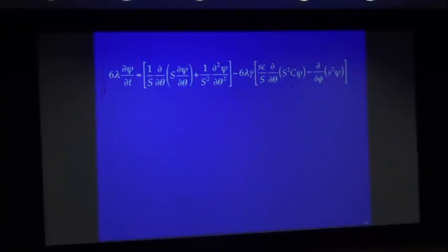This term here, you notice, does not contain the shear rate. This is the Brownian motion term. This is the term that if I turn off the shear rate, this will make the system spherical again. The orientation distribution function spherical again. And then this is the convection term. This is the term that when I turn on the shear rate, and in my case it's a cosinusoidal shear rate that I'm interested in, that will affect the orientation distribution.